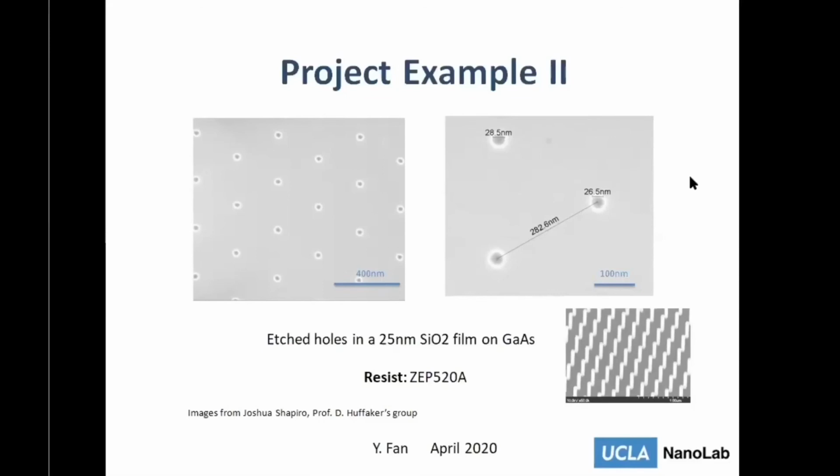To minimize the drift, there are a lot of things to be considered. For example, the temperature mostly. That means if you really want to improve your stitching, you might have to wait a while. Just to give you an example, you might have to wait a while after loading the sample into the chamber before you start writing. Definitely a tiny temperature shift really matters in that respect.